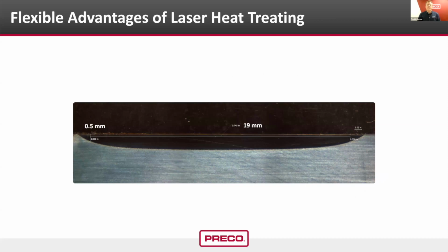This is a typical heat treating track profile. You will see the elliptical sides in this picture. Keeping that in mind, when you're looking for a certain case depth, make sure you have enough width in the optic selection to accommodate that.